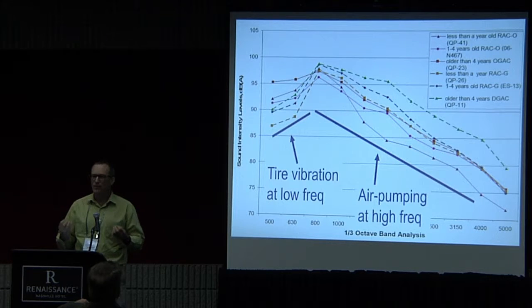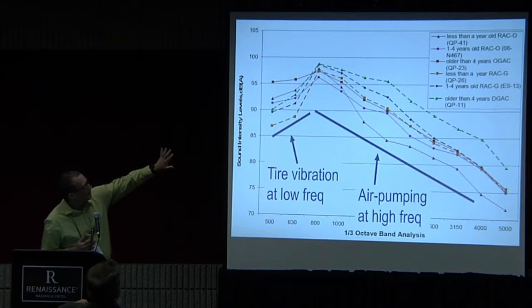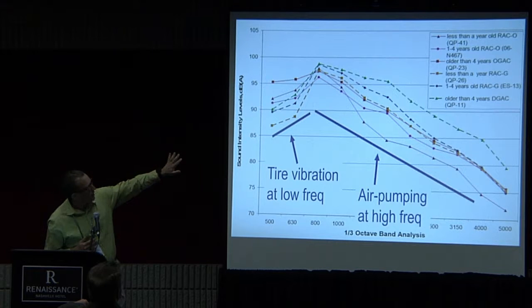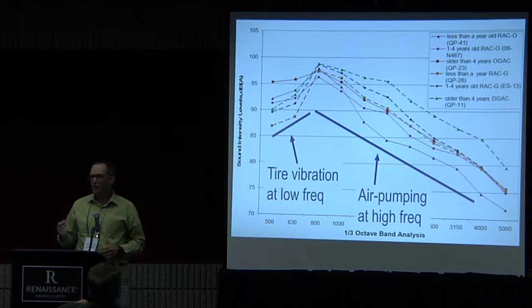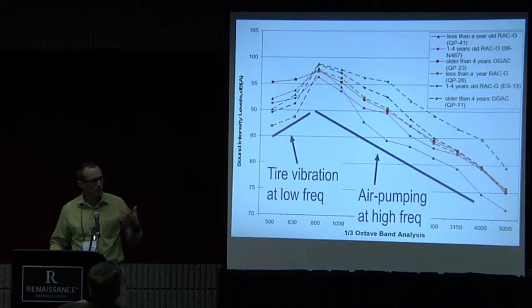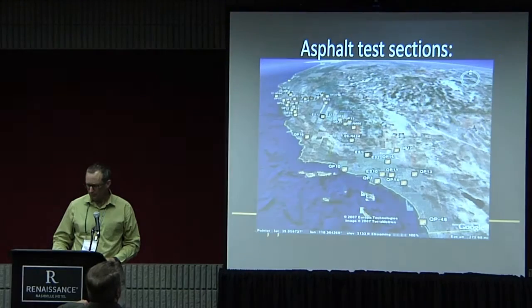So there's a part of this tire pavement noise that we can't actually control, and it has to do with the aggressiveness of the tire tread in there. But we can affect to the left of that to some degree, and to the right of that to some degree, particularly with our preservation treatments, because we're treating the surface and dealing with texture and porosity of the surface.